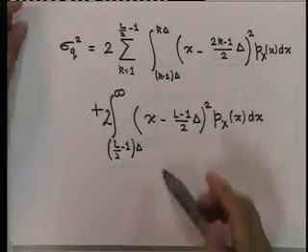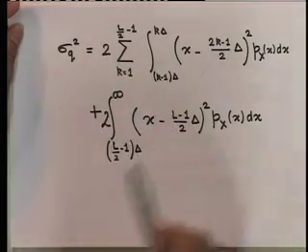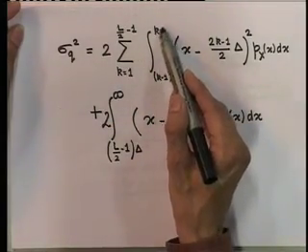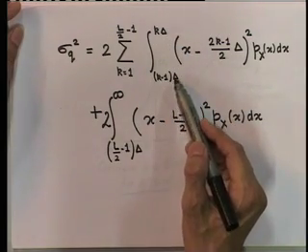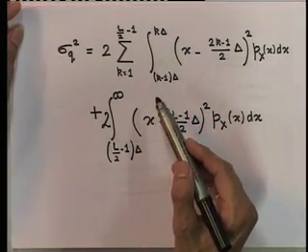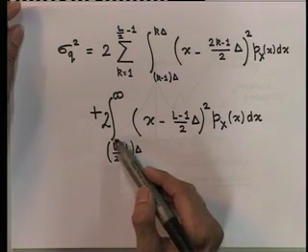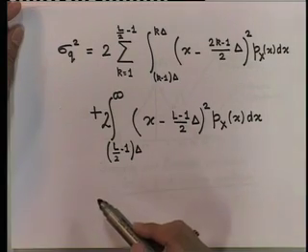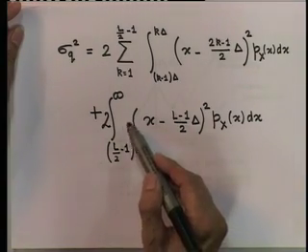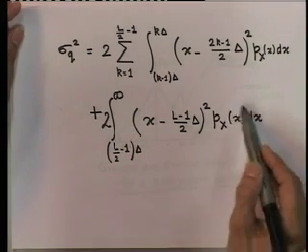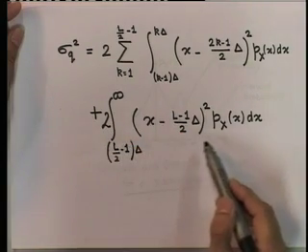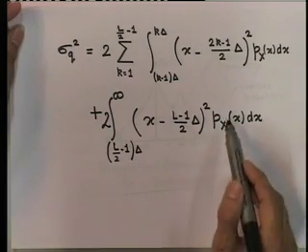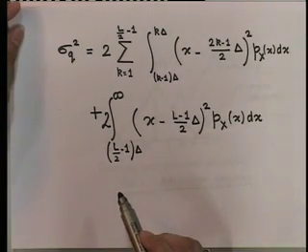Now, from this equation, it is clear that if we increase the step size delta, this will result in an increase in the value of (L/2 minus 1) times delta, which in turn will result in a decrease in the overall overload probability and therefore the overload noise.